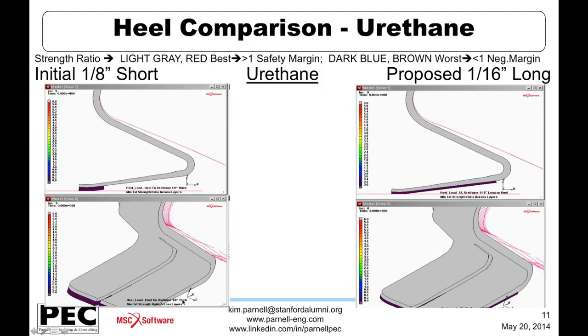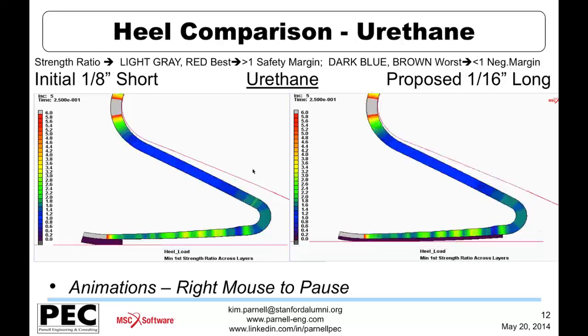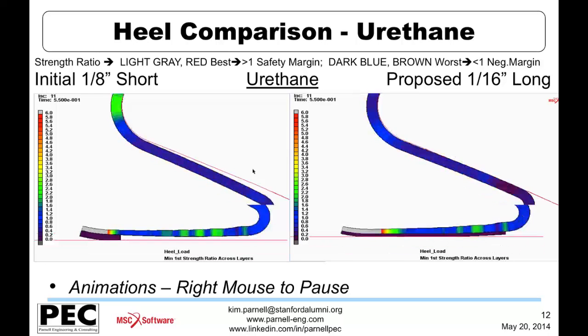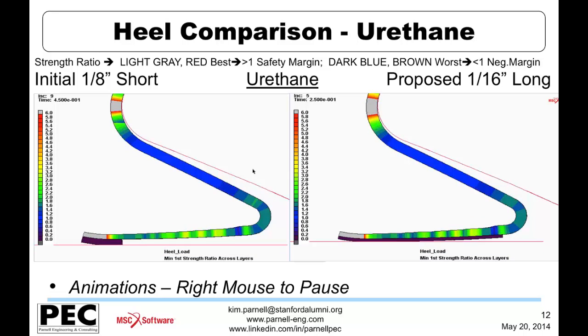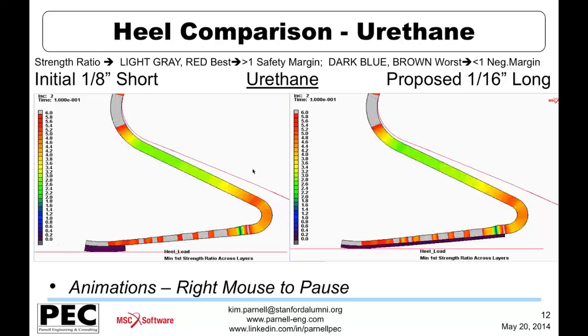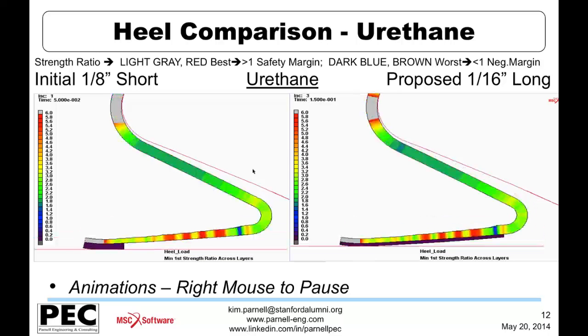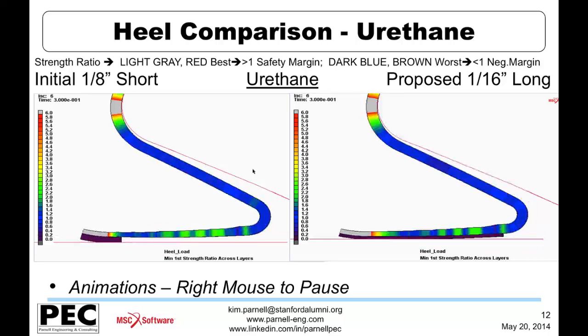And again, a couple of different views of looking between here. The component that we're going to look at to make some assessment of effectively overall stress levels is the strength ratio. The strength ratio is a very useful value in assessing composite materials where you have significantly different strengths. You have orthotropic material behavior and significantly different strengths in the different directions.